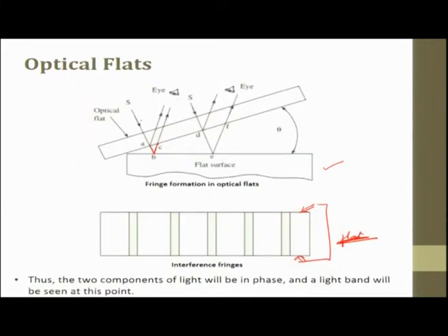So, what we are trying to say is, this is an optical flat, a flat surface. If you want to measure the flatness of a surface, we use an optical flat. Both the surfaces are flat and the light from the source falls on it. It reflects at A, reaches the workpiece, reaches the flat bottom side and goes. So, if we say this is lambda by 2 and this is 3 lambda by 2, then we have total interference happening. It is placed at a small angle theta.